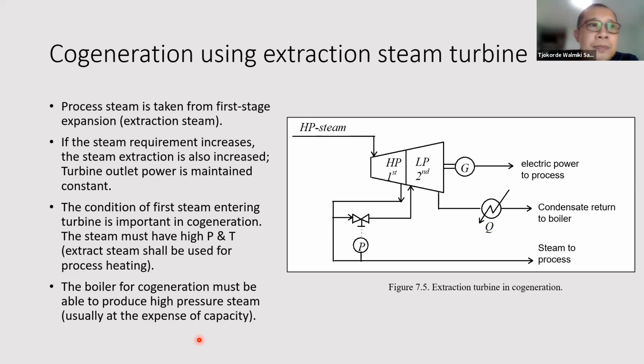So in this case, it depends. There are some rules of thumb. If you read some books, they will give you a rule of thumb for a minimum, not just the delta T, but a minimum delta T for a good heat transfer rate to be 10 degrees Fahrenheit. Some people say it's 10 degrees centigrade, 10 degrees Celsius. You can use either way.